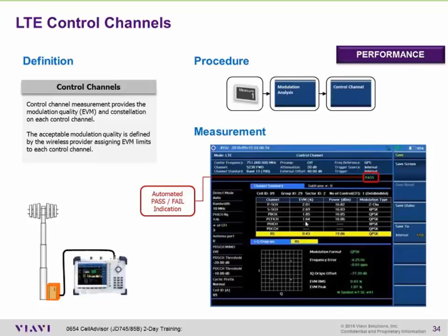If you do get a higher than expected error vector magnitude value, and you otherwise have what would be considered ideal RF conditions, because you're hardwired into it or you've created pilot dominance and minimal multipath power, this is what the constellation or the values of the error vector magnitude should be approaching. Again, this is probably a hardwired connection because these values are actually quite low, meaning very, very good.